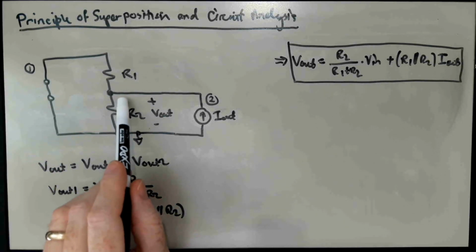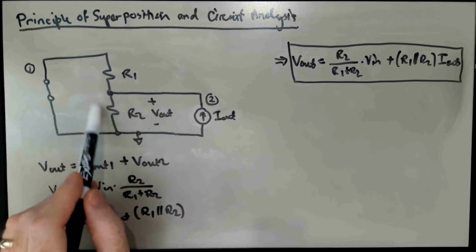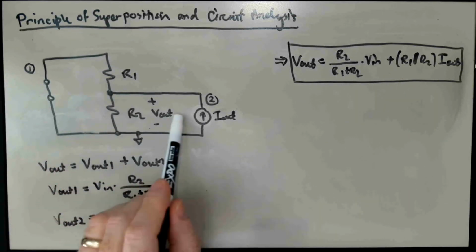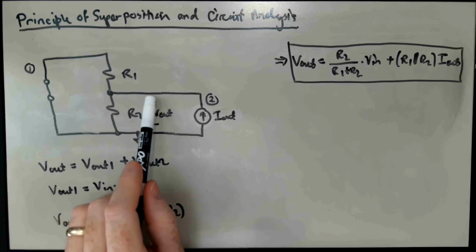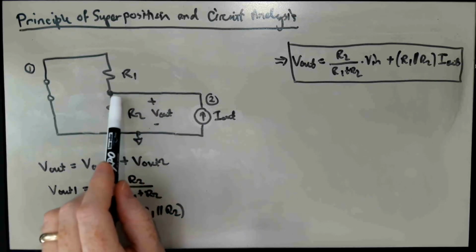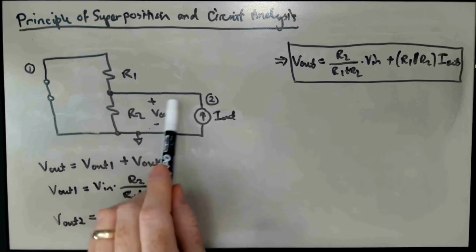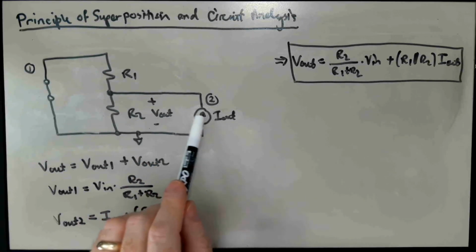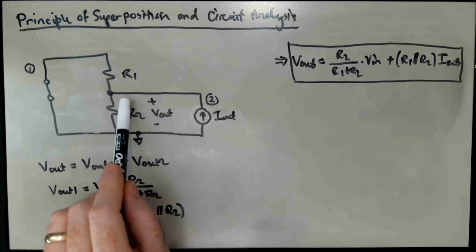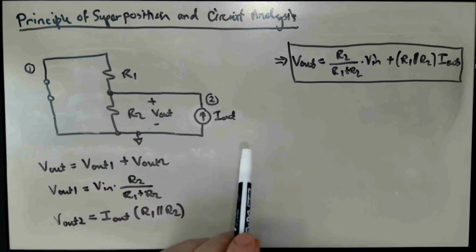In order to be shifting only by millivolts, if I had kilo-ohm resistors here, I would need to be drawing out microamps of current, which is 10 to the minus 6. And so very often we'll need to buffer this voltage divider so that the op-amp buffer would supply the current that is needed by whatever we're connecting this to, and we don't disturb the voltage on this middle node. A lot of times people forget that.